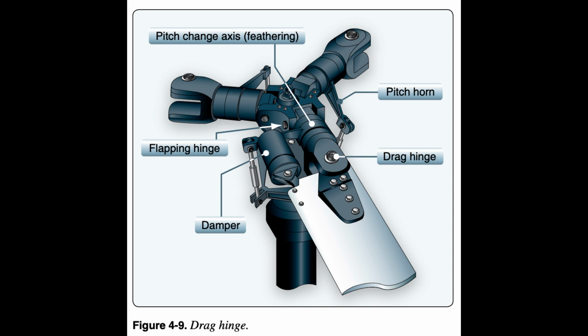Older hinge designs relied on conventional metal bearings. By basic geometry, this precludes a coincident flapping and lead/lag hinge and is cause for recurring maintenance. Newer rotor systems use elastomeric bearings, arrangements of rubber and steel that can permit motion in two axes. Besides solving some of the above-mentioned kinematic issues, these bearings are usually in compression, can be readily inspected, and eliminate the maintenance associated with metallic bearings. Elastomeric bearings are naturally fail-safe, and their wear is gradual and visible. The metal-to-metal contact of older bearings and the need for lubrication is eliminated in this design.